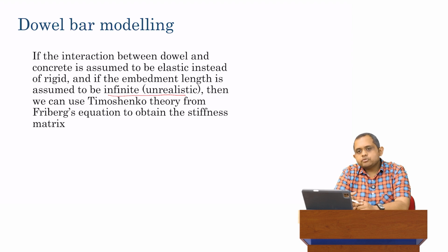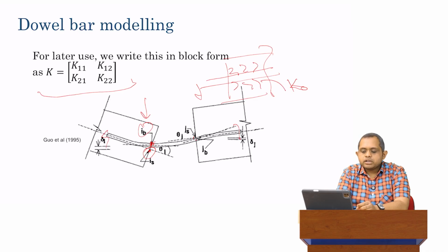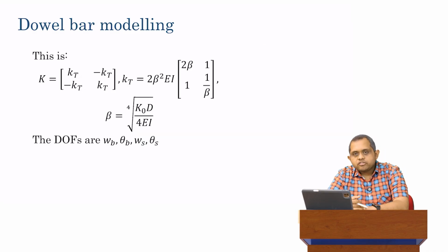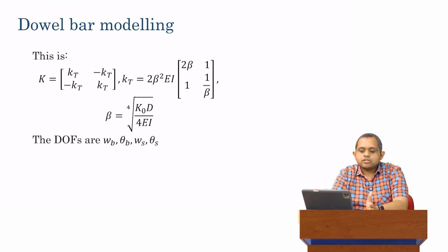You had some elastic modulus over here. If we go with that assumption from a finite element perspective, then we can still do this analysis. So we can model the tiny piece over here using a Timoshenko beam. We can model the rest of it using an Euler-Bernoulli beam, and that Euler-Bernoulli beam is infinite in length, and it's embedded in this bed of springs. And so the stiffness matrix that we get, if you make these assumptions, can be written in this manner.